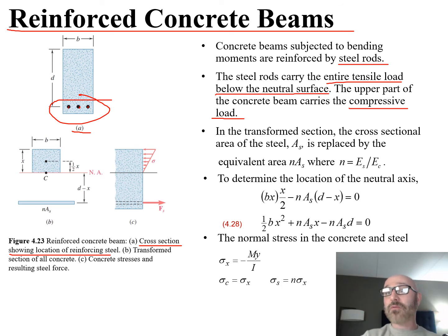So if we're going to do that for a three-point bending like that, which you typically see on a bridge as a car drives over, it's going to bend down like that, compress the top layer, and put the bottom layer in tension. We put these rebar in strategic places right there.